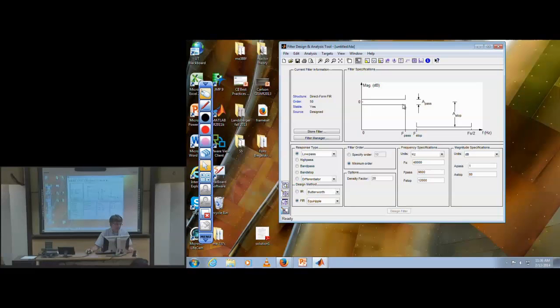Why do you care about the magnitude of the pass band ripple? Well, we're going to see, there's lots of reasons for that. Again, the ideal is you'd like to have exactly 1 in linear units or 0 dB. If you could have a flat pass band, it would be great. We can't give you a flat pass band, so it's going to wiggle. We're back to wiggles now.